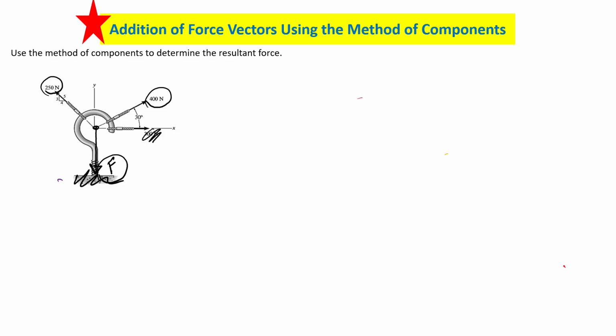If there is a resultant force, we can't say it is in equilibrium, so resultant force is zero. So when you draw the vector diagram, the resultant force is given by start to end. Am I right? Resultant is always given by start to the end. If the resultant is zero, your start and end are equal. Agree? So it should make a closed polygon. Do you agree with that?